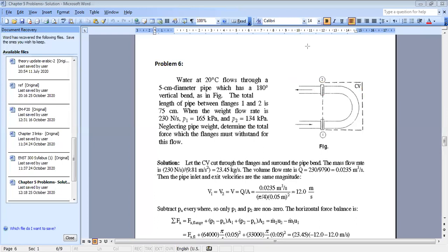Imagine it in another way. Here you have P2 and here you have PA. If you want to find the resultant X force here, what will be your resultant X pressure? Here I have P2 from this side and here I have PA. What is the resultant pressure for these two? P2 minus PA. Yes, exactly. Because you can divide this pressure P2 into two parts, PA and another component which is P2 minus PA. So when you divide the pressure into two, P2 minus PA and PA, when you calculate the resultant force, the effect of these two will cancel out.